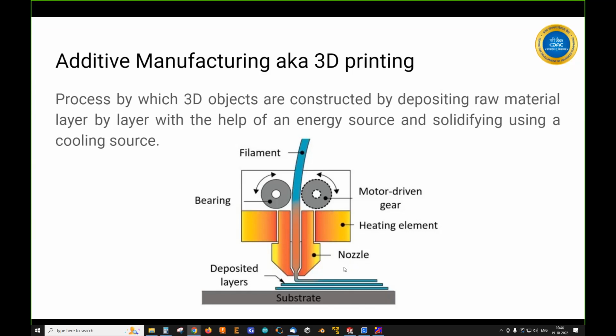In general, if you search for additive manufacturing, you will mostly see a technology called FDM, or FFF, fused filament fabrication. In that, plastic filament is fed into a nozzle. You can see this is actually an example of FFF only. Anyhow, this is not the only technology. There are 7 technologies, but I'll explain that.